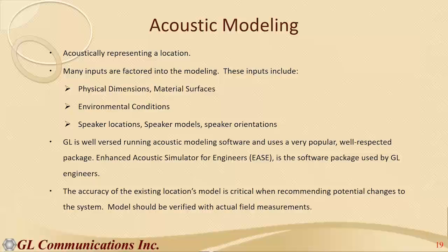You draw your model in this CAD program, and you enter all these dimensions, speaker locations, all this stuff gets entered into the model. Then the model itself produces the expected STI values for that location. Now, what we've previously done is we've had our field crew out there actually measuring the STI values. We bring those back, we compare them to the model.